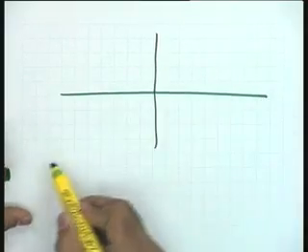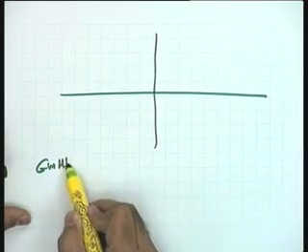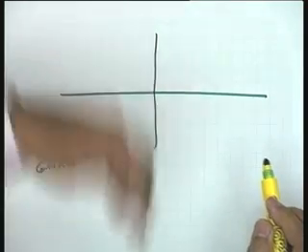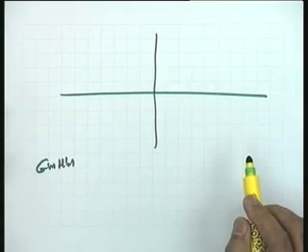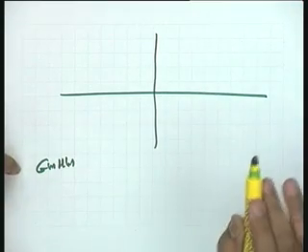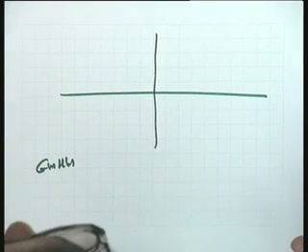Okay. And the criterion which we finalized last time is the following. I take the map of the function GSHS when S moves along the contour I have just now given, called the Nyquist contour. So, you make a plot of GSHS; this is the total exercise you will have to do.